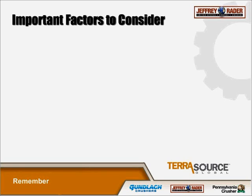A few things that are pretty important to consider. You want to try and keep the blower located fairly close to the feeder. It's possible to have the blower far away. A lot of times that's the only scenario, and in that case we just need to know the piping routing from the blower to that feeder so we can calculate the pressure losses from the air.